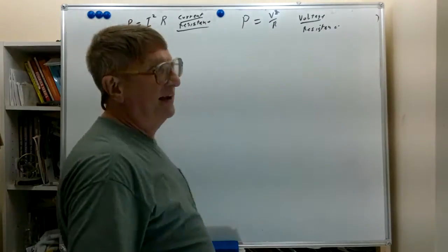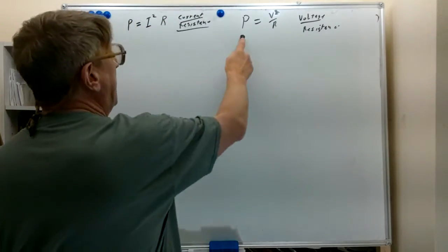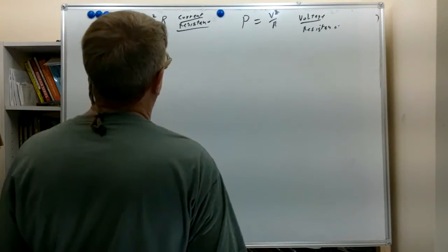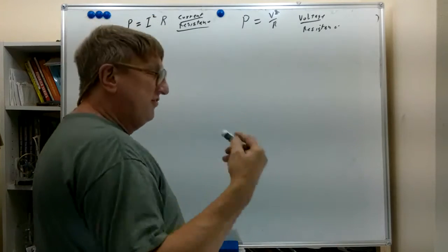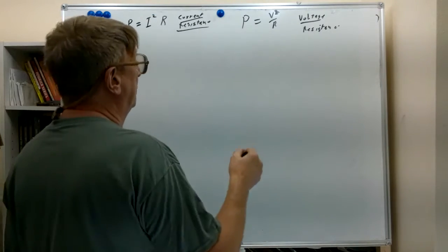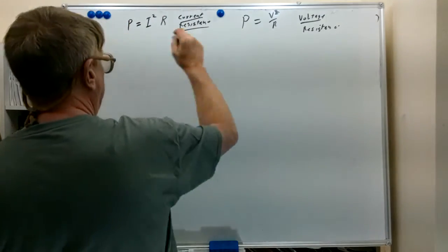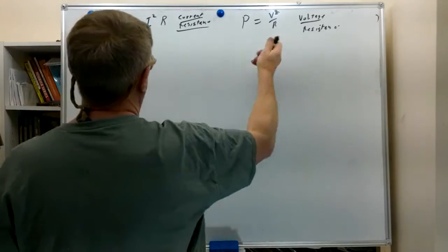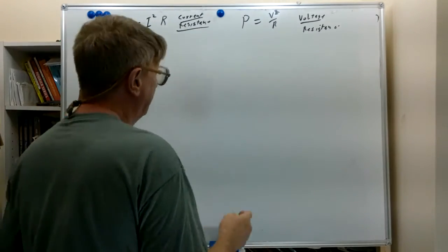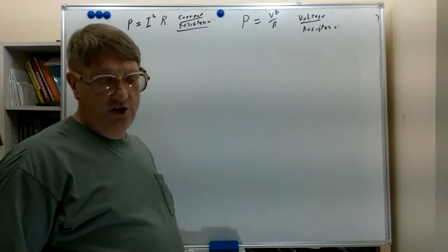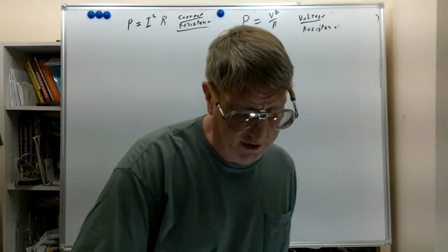1 watt per 1 second gives you the 0.24 joules we talked about. So the heat is actually power times the time. But we express power, and the energy dissipated in the resistor in terms of heat, so it is handy to have power formulas that are expressed with resistance. So here we've got current and resistance, and voltage and resistance. All these are useful, but this one we might find to be quite useful.